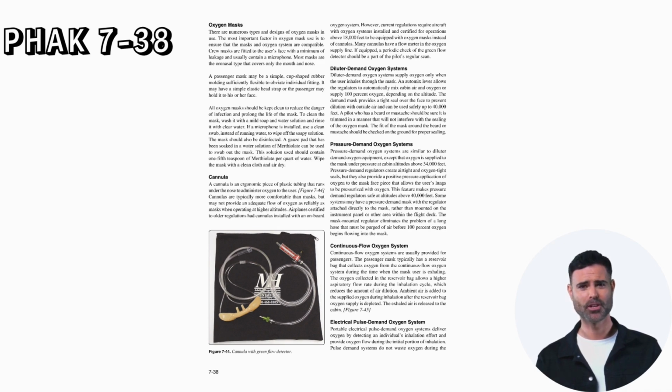However, current regulations require aircraft with oxygen systems installed and certified for operations above 18,000 feet to be equipped with oxygen masks instead of cannulas. Many cannulas have a flow meter in the oxygen supply line. If equipped, a periodic check of the green flow detector should be a part of the pilot's regular scan.